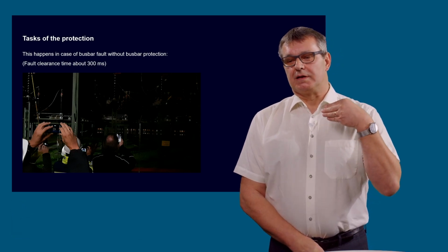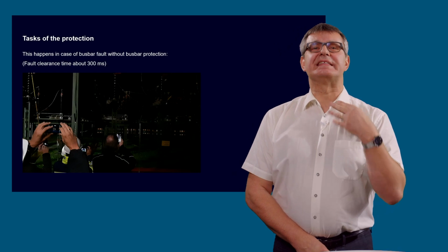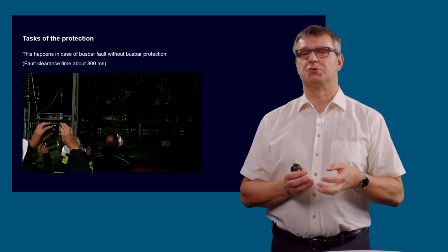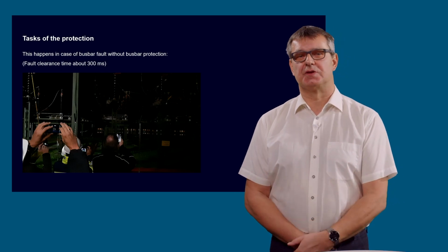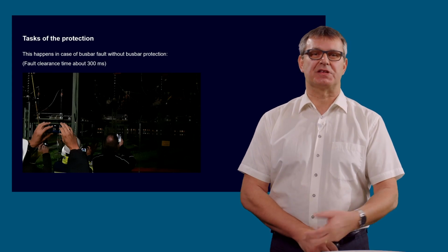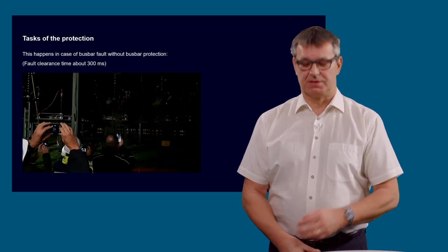how necessary a dedicated busbar protection really is. In high voltage, to have only a busbar protection with a backup protection of 300 milliseconds of the distance protection is really not state of the art.